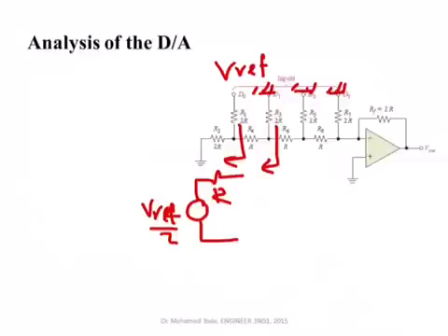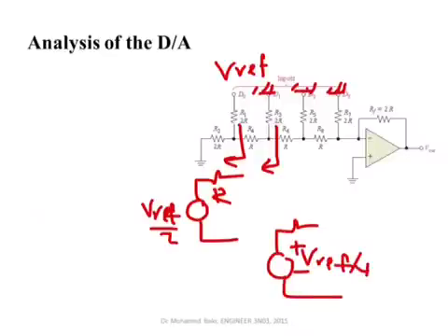So looking at this specific point here, I'm going to be seeing a resistance R and then a voltage of Vref over 4. Okay? So now we repeat the same thing again. You have R in series with another R, then you get 2R. And then in parallel with these 2R, the equivalent Thevenin looking into this circuit from this side is simply equal to R. And so on.